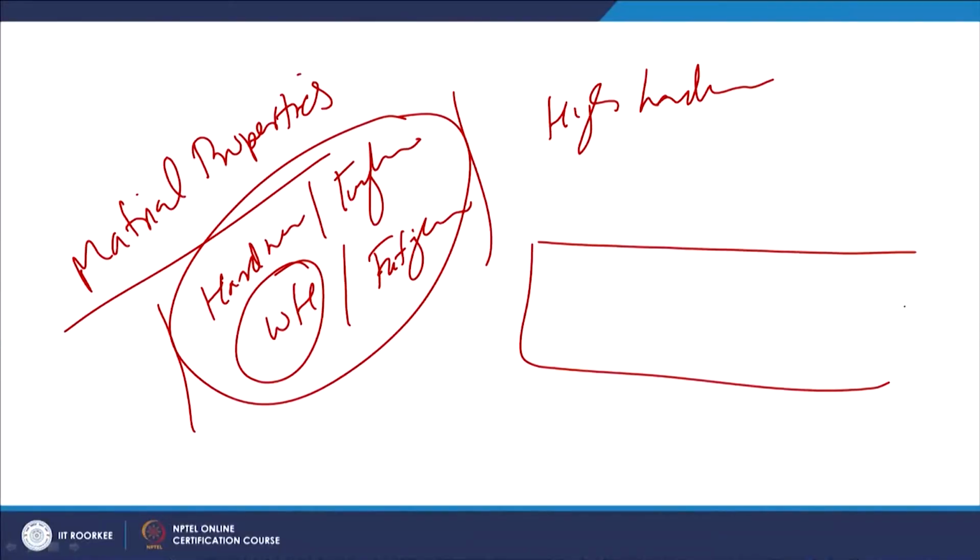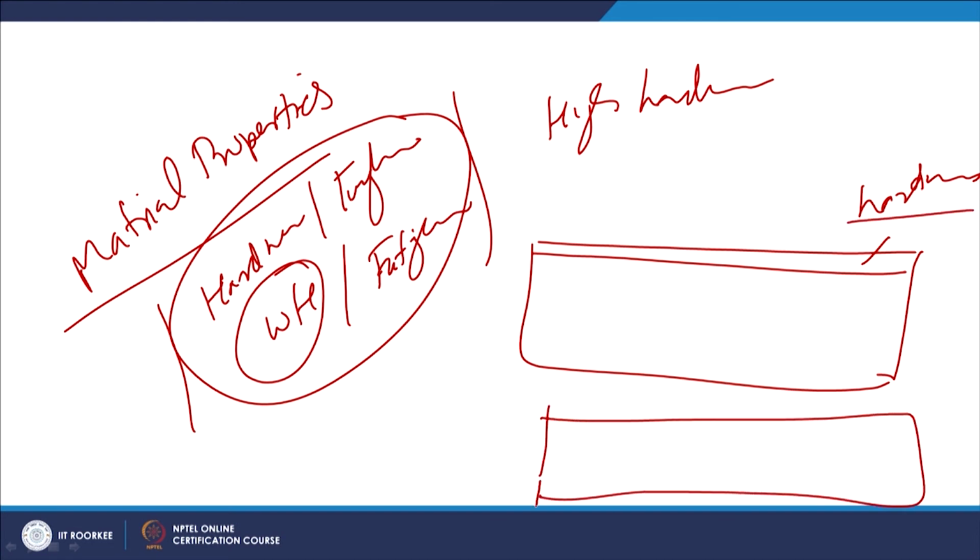So, say in case of low angle erosion, we need to have good hardness, while in case of high angle impingement, it is required to have good toughness as well as fatigue resistance, so that the crack nucleation, micro fracturing and micro cracking tendency can be reduced.